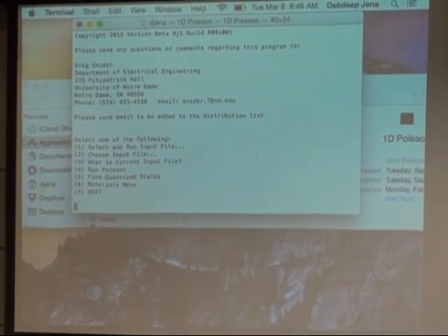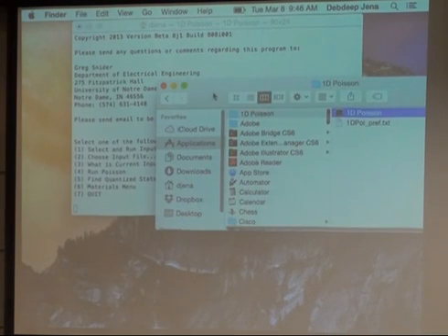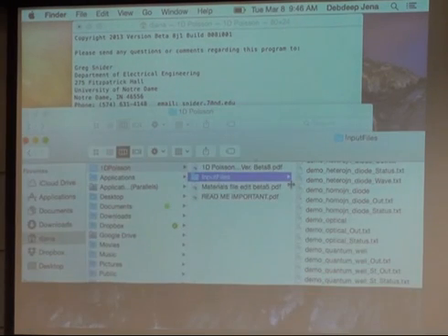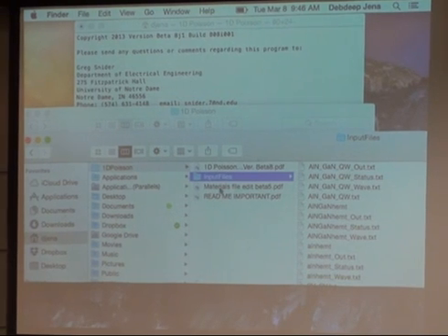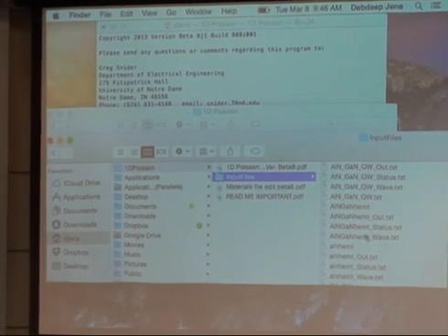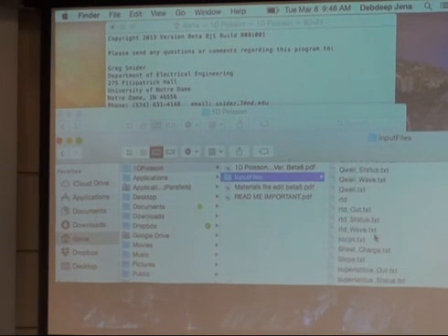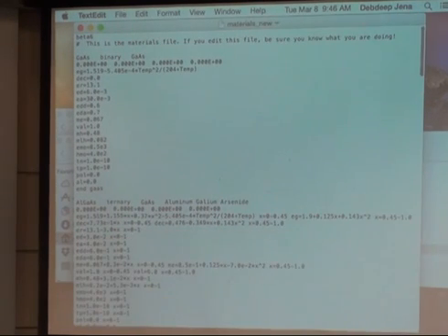You can see it has a few things here. But what I want to show you is that the program needs a materials file, which it downloads into the directory. It will give you some README and some materials file information here, so please read that up, and let me look at the materials file. So here's the materials file, for example. Everything we have done about the band structure, about doping, about band gaps, all that stuff is here. Effective masses, everything is inside here.